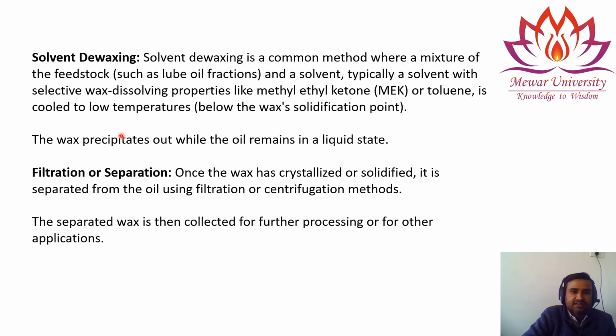Solvent dewaxing is a common method where a mixture of feedstock such as lube oil fractions and a solvent, typically a solvent with selective wax dissolving property, is used. The solvent we use has an affinity towards the waxes, so it can dissolve wax into it. These kinds of solvents are basically methyl ethyl ketone, MEK, or toluene, and the mixture is cooled to a low temperature below the wax solidification point.